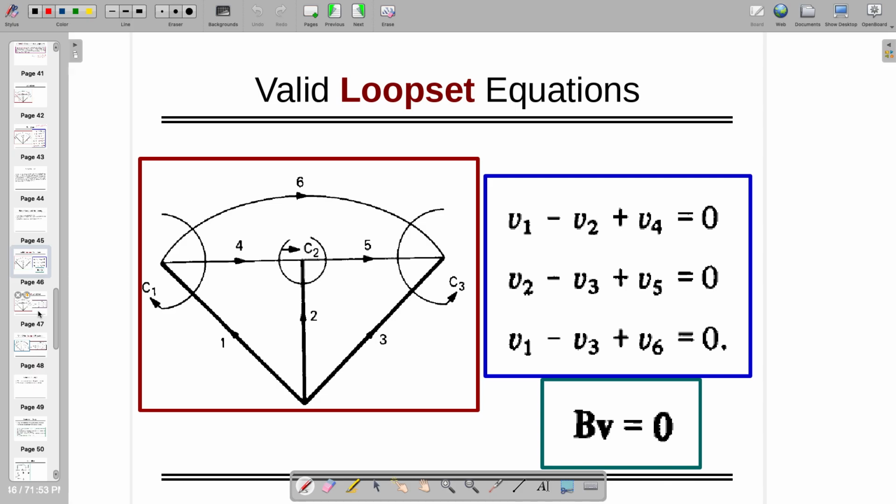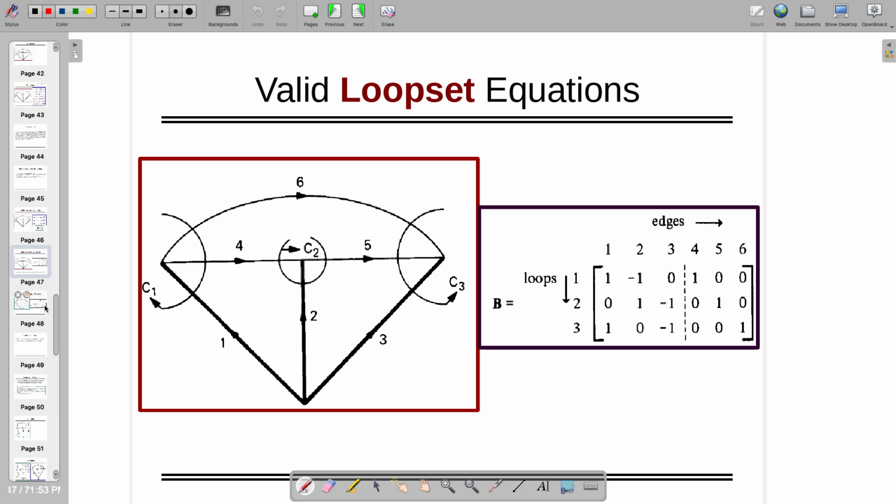So you can write down the following equation. When we are doing this, it's happening for a particular tree. One can have a different tree also. If somebody takes a different tree, the answer will be different. As we decided, rename them to 1, 2, 3 for the twigs and the rest 4, 5, 6, so that the matrix is uniform and the last part is diagonally 1.